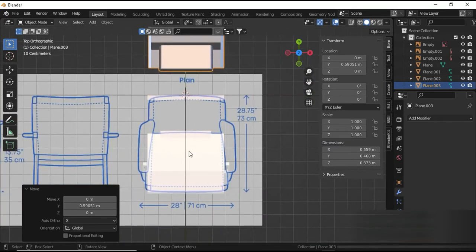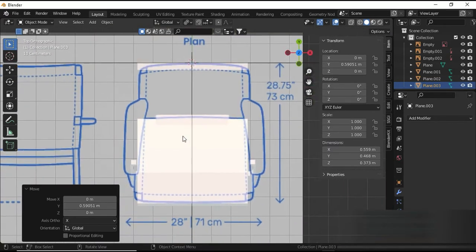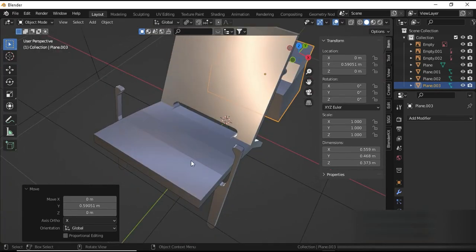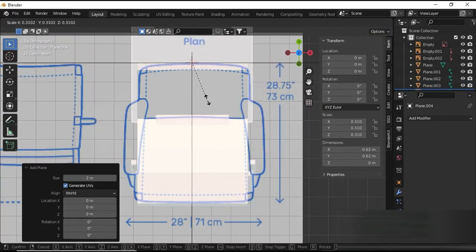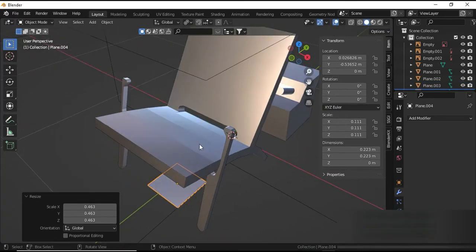And make sure to run the checks. The first check is of course the scale, the second check is the normals, and the third check is merging the vertices, which can be done by Edit, Select All, and M.